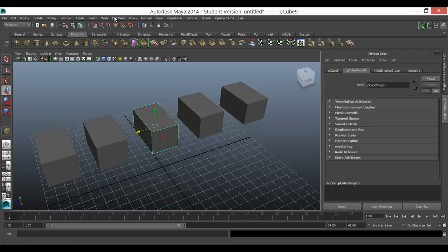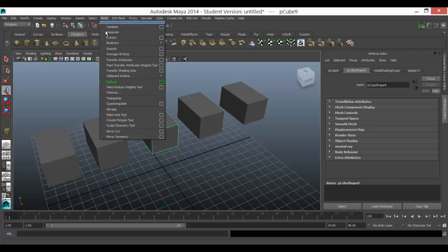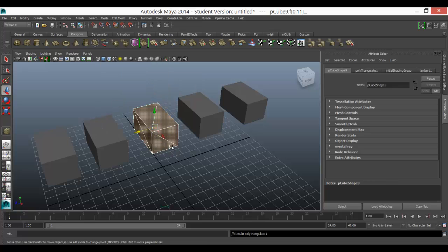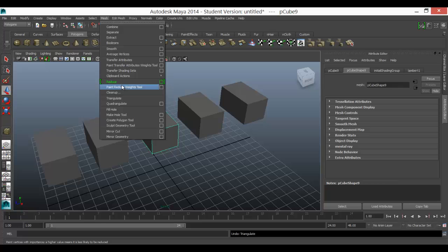But you can also use triangle models as well, and if you have something selected, you can see there I can triangulate a polygon model, or I can quadrulate it if I want to instead. So a lot of the tools in here are about controlling the faces, and the faces are made up, and cleaning up faces and models once you've started using them.